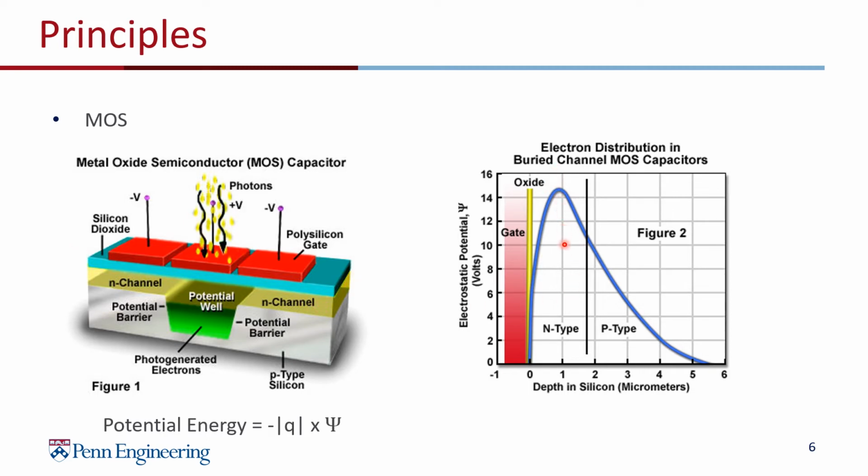When the CCD is exposed to light, each image element has an electrode at a high potential. The potential under this electrode in the silicon wafer will increase and become the place where the photon electrons are collected, which we call a potential well. The electrodes near it form a potential barrier and define the boundary of this image element.